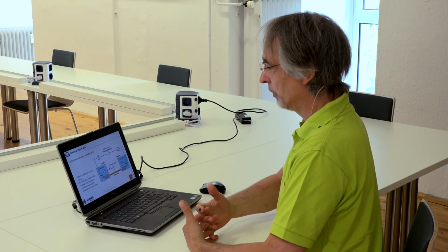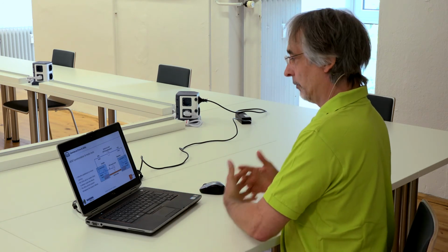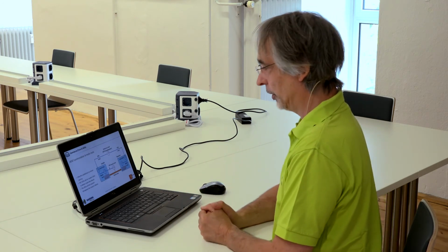So since the RTP clock is part of the stream data, if we use encrypted stream data and we knew the exact value of the RTP clock, because it has no offset to the media clock, to the network clock, then we would know values inside the encrypted part of the stream. They wanted to avoid this, and so they called for a random offset for each individual stream which has been created and sent over the network.